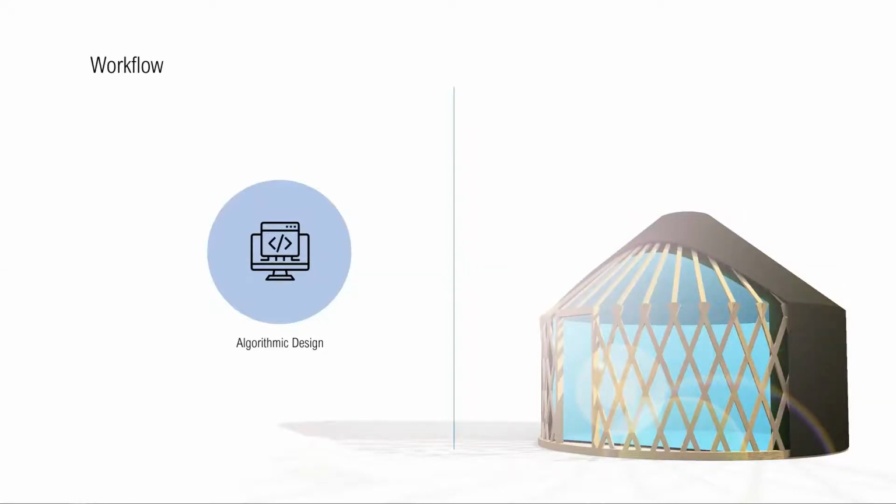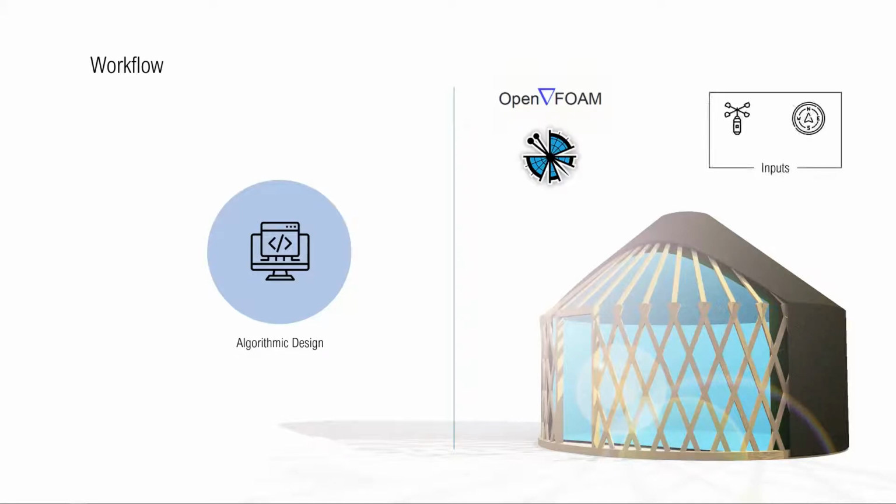In this case, for the airflow simulation we used OpenFOAM with Butterfly to simulate outdoor airflow using the specified inputs. We tested the most extreme case in each month since last year's expedition, which was 70 knots from the east. Moreover, we tested the main wind directions during that year with the maximum speed value.